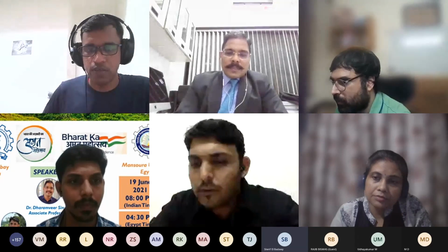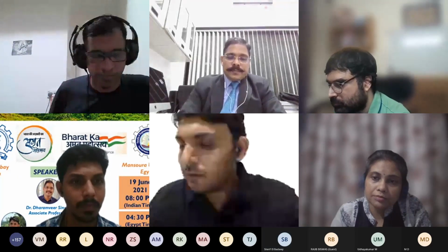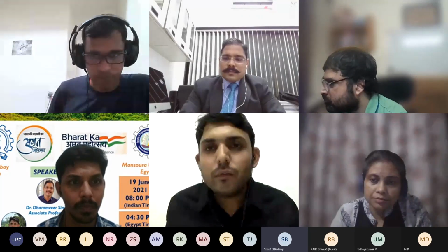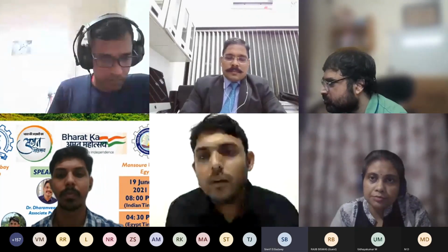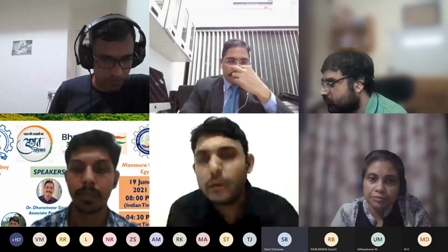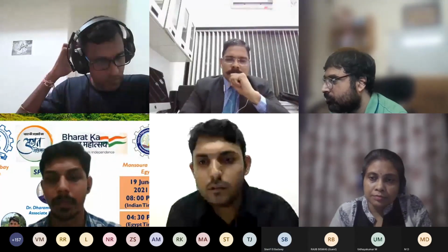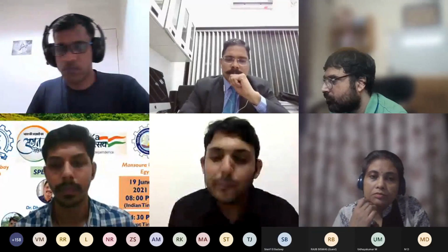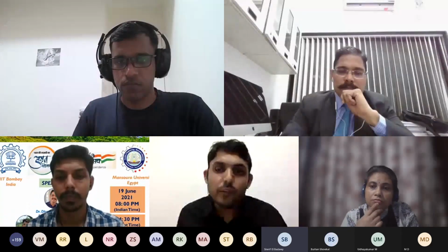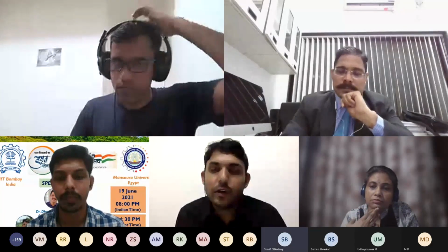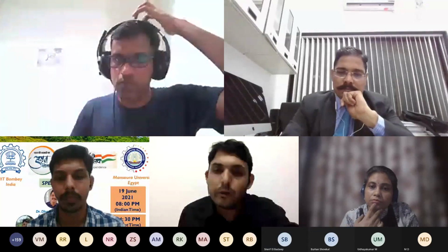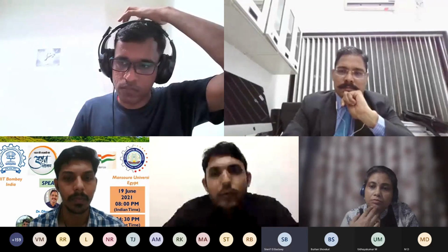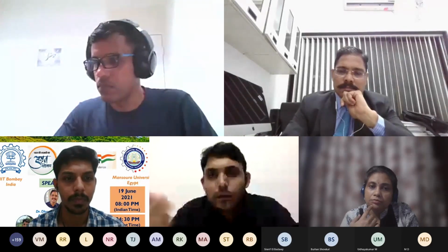Yes. First, I think that question was asked by Mr. Nagendra. If you see the Indian values we are using for the UCS in cement stabilization, it's around 4.5 to 7 MPa. And if you see international literature like the California Transportation Department, it's not that we should go ahead with higher values of UCS.